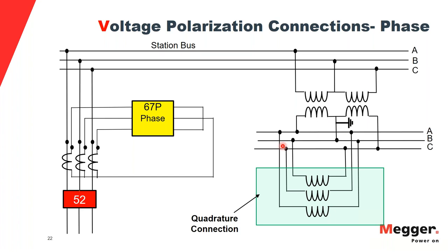This is a low voltage line, and I'm basically measuring voltages from here. So you see that the phase connections for any directional relay, it's going to measure phase currents, right? The currents would be from the phase CTs. And what about the voltages? I explained to you that if it's a phase A fault, I have to sense B and C voltage line to line.